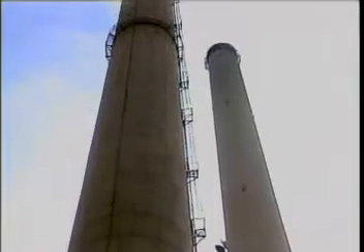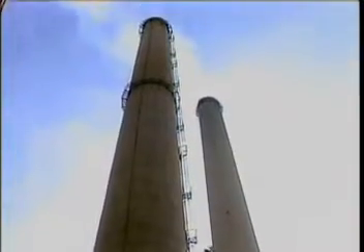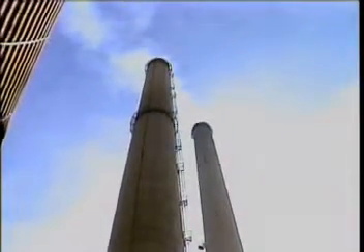In practice, how do you think the fuel-air ratio is adjusted to make sure that all of the fuel is burned? By making sure that all of the fuel is burned, you reduce the possibility of an explosion caused by unburned fuel building up in the boiler or in the stack. Since excess air is supplied to the wind box, there should always be excess oxygen going out the stack.